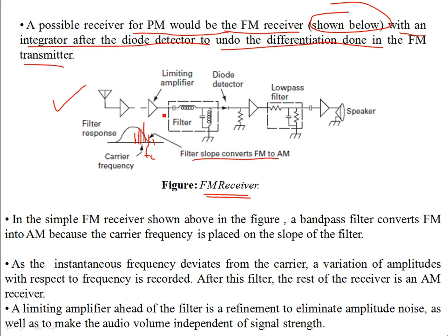You have a filter over here. If you look at the circuit topology of the filter, it's a bandpass filter. Why is it a bandpass filter? It consists of a series LC circuit before a parallel LC section, and you set the resonance frequency, 1/√(LC) of this filter, as the center frequency of the bandpass filter, let's call this F0. At the center frequency, the series LC will be a short circuit, and at resonance the parallel LC will be an open circuit. So basically at F0 you will have the signal feed through this filter with the minimum possible attenuation.